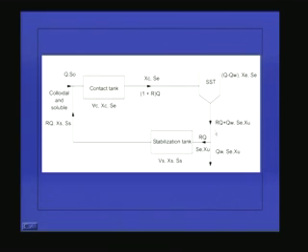And here, a portion of the sludge will go out and the remaining will come to the stabilization tank. The flow rate is RQ, the soluble BOD is Sc and the biomass concentration is Xu. And this is the volume of the stabilization tank, Vs, with Xs and Ss.